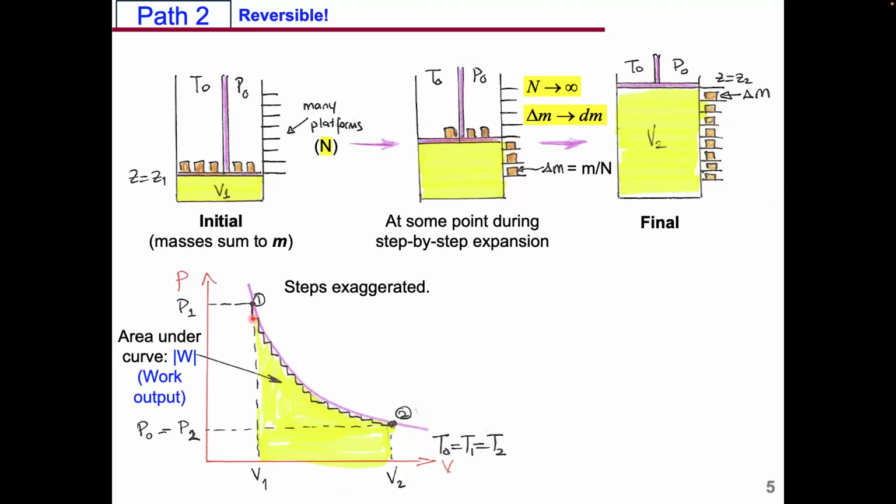Equilibrium means the system will expand, right? So V2 expanding to this value. While it's expanding, the system pressure is dropping from here to here. And then when it reaches equilibrium state, your system pressure is equal to external pressure. So it will rise here, okay? And then you take another one, same thing, and again, same thing. So basically you move from point 1 to point 2 by many different small steps.